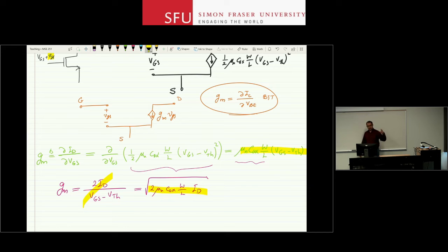The end point is that it will be the slope of the ID versus VGS curve, right? So we have the quadratic curve between ID and VGS. Well, this is more like an exponential now, right? So this is VTH. Before that, you don't get anything. And this is your bias point, assumingly. So this is the slope here, and that's the value of gm. Calculate gm from your DC analysis, put it in that model, and then, bingo, you have your small signal model for your NMOSFET.